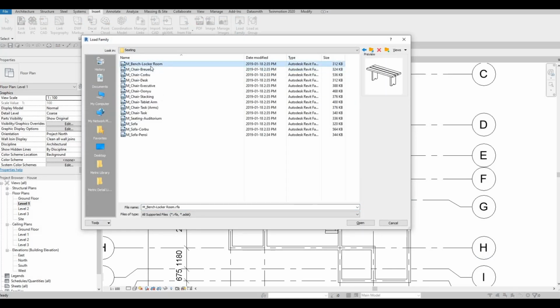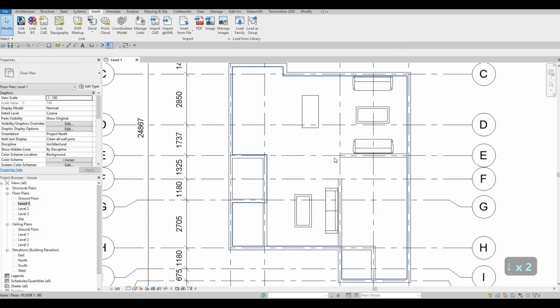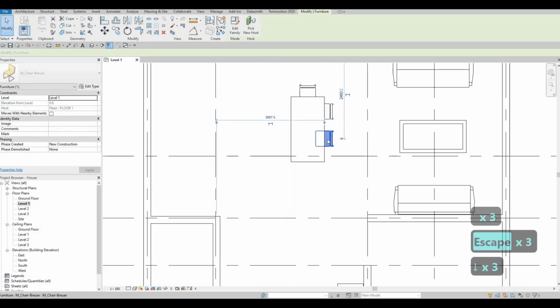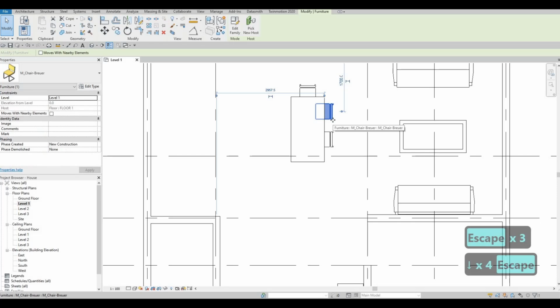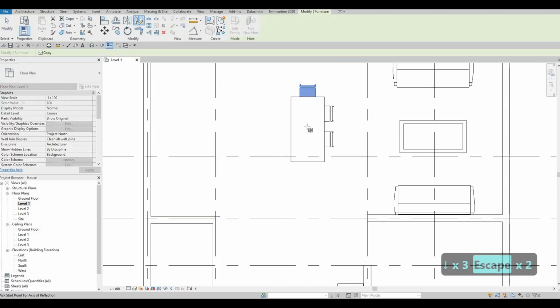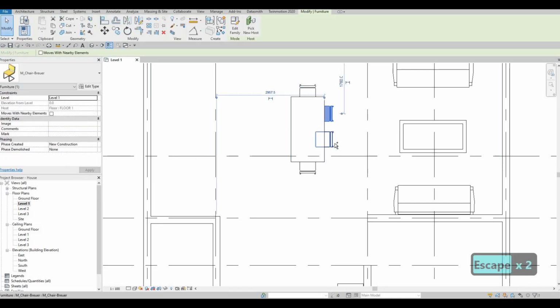And then let's go to seating so that we could add this chair, CM, and then add those seats right here. Usually I put it in one area first, or in one side, and then after that I use mirror, and then mirror on this side.